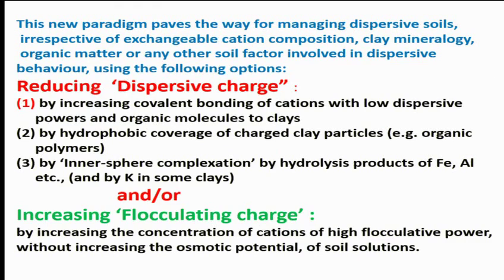We don't worry about what is the exchangeable cation composition. You don't worry about what is the clay mineralogy. Clay mineralogy indirectly matters, but we don't worry in terms of management. Then we don't worry about organic matter affecting this and that. What is important is you have to reduce the dispersive charge.